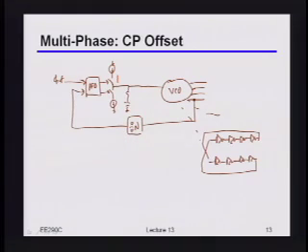I'll give you guys a hint or a reminder. There was one particular thing that we talked about in some reasonable amount of depth that caused a problem with static phase offset. Anyone remember what that was? I heard somebody whisper it. Just have some mismatch on the charge pump current.